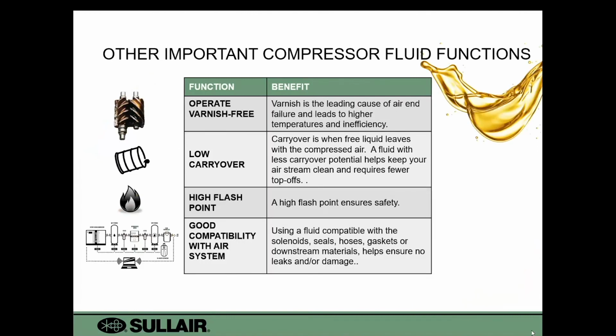Some other important functions are to operate varnish-free. Varnish is your leading cause of air end failure. When you start to form varnish, it varnishes up your coolers, which leads to higher temperatures. It also causes a power penalty for you for getting the air that you need. You also want to have low oil carryover. When you have higher oil carryover, you have more fluid going downstream, affecting your equipment, but also costing you more in top-off fluid.